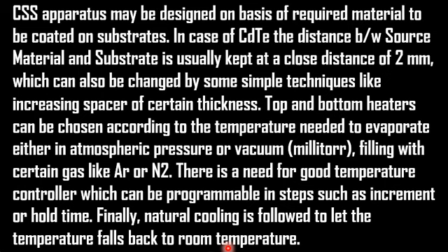Another interesting fact to notice here is that the closed space sublimation apparatus contains gases like nitrogen and argon. These gases act as transporters. They transport the evaporated precursor material from the precursor onto the surface of the substrate, which at the end of the day is converted into a thin film.